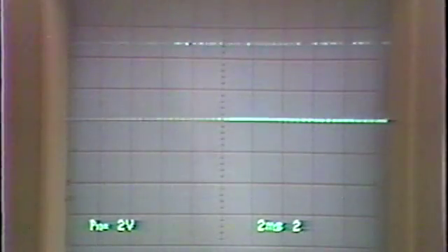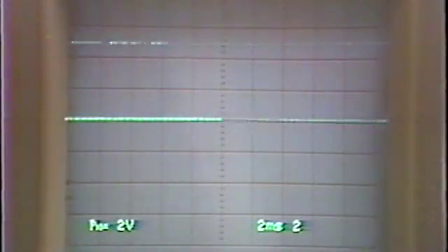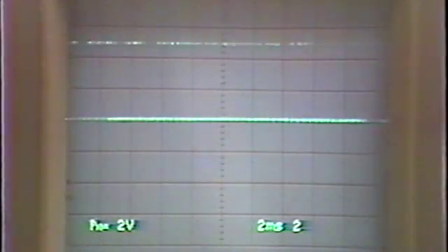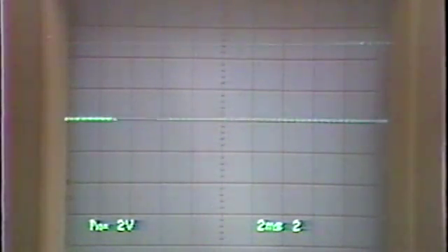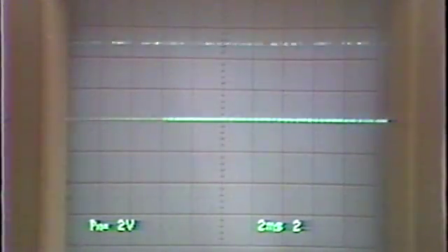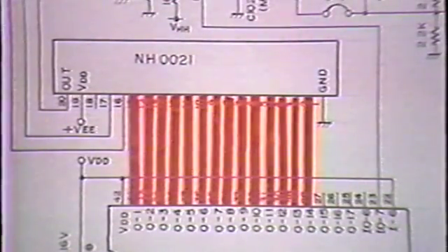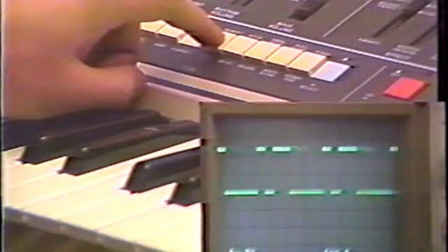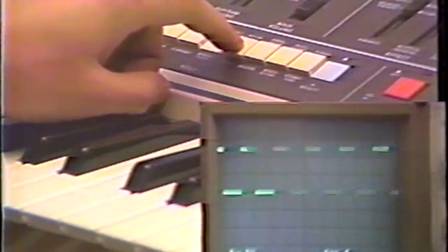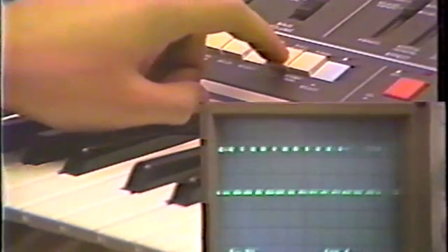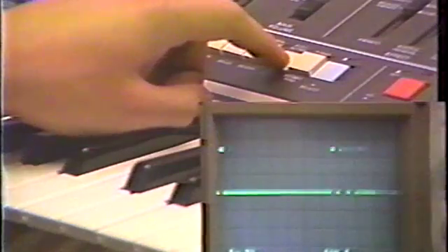The CPU constantly sends the set tones and data from each switch to the melody LSI, so signals like these can be observed by monitoring the data bus with an oscilloscope. When the melody LSI receives data from the CPU, it outputs 14 types of digital signals from O1 to O14. This is the O1 waveform. It will vary depending on the voice and the pitch.